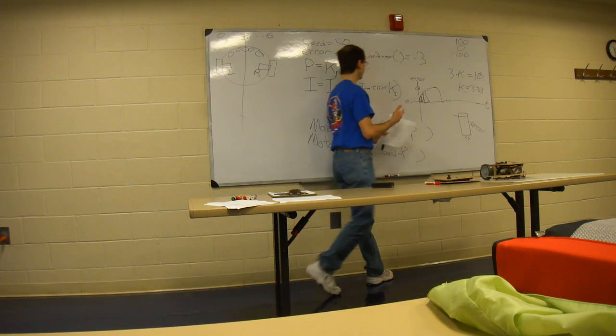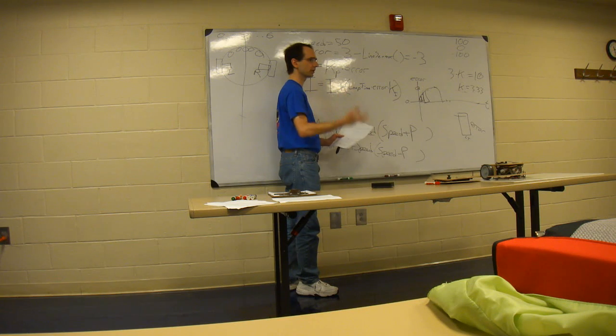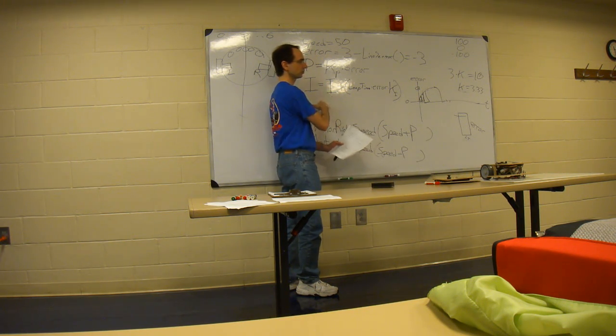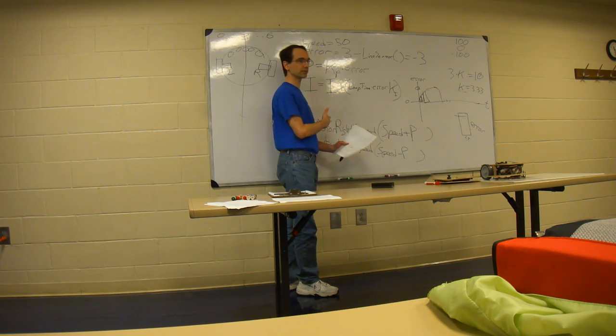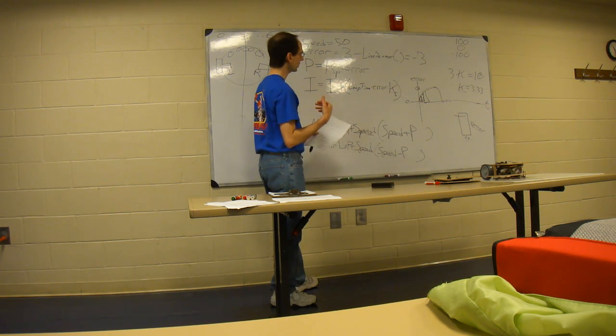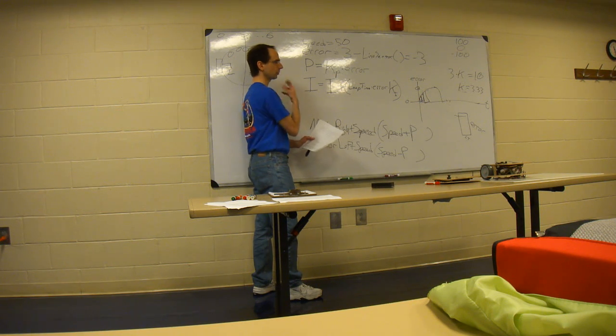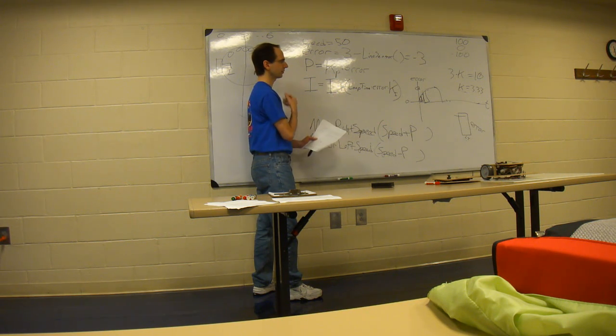So when you're using I, you have to watch out for the possibility of overrunning your motor, overrunning your heater, and that sort of thing. This term will just continue to grow and grow and grow if you get stuck on one side or the other. The I term is a very important term if you're worried about getting stuck, if you've got a lot of friction in the system. But if you don't have a lot of friction in the system, if you're not that worried about getting stuck, the I term is actually rarely used.